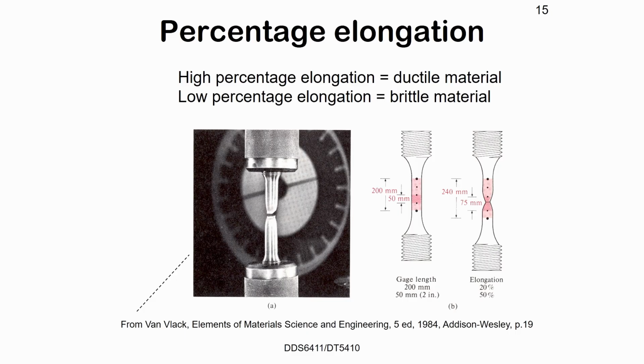So the actual stress-strain curve, if you use the actual area, will keep on going up. It won't be linear, it's non-linear, but it will not be decreasing. It's decreasing purely because we are using the original cross-sectional area to calculate the stress. If you account for the reduction in the cross-sectional area, then the curve will be going up. Thank you.